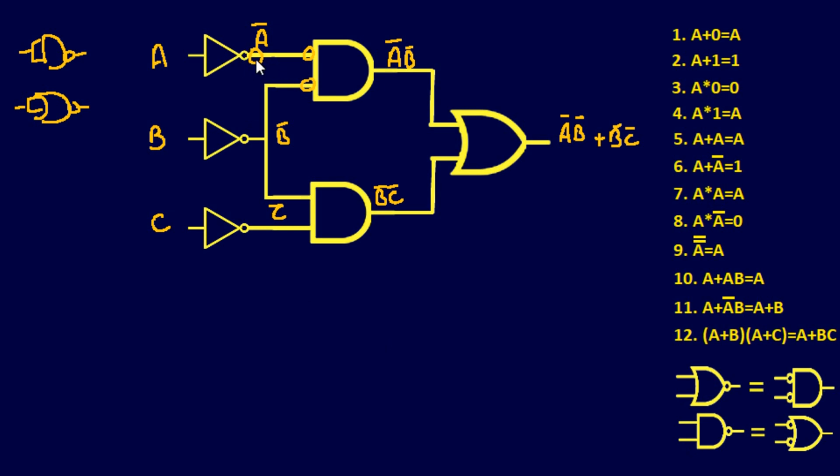So these 2 dots cancel out, which is great. This looks like a NOR gate, so that's great. But unfortunately, I put a bubble right there, so I got to put a bubble down here too. Anytime you create a bubble, you gotta put one on the other side. We'll do the same method down here too. Bubble right there. I already have a bubble compensating for that one right there. Again, as long as you put one at the other end, you're good. And then I'm gonna put a bubble right here, and then a bubble right here. So that would actually cancel this inverter out as well.